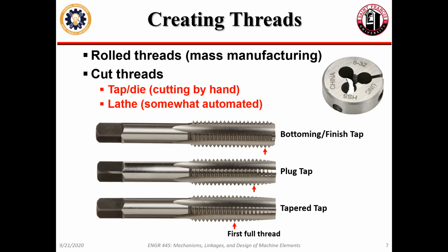The more threads you're trying to cut, the greater force there'll be on the tap itself because of how they're made. So most of the taps you'll see around here are tapered. So start from not really anything. This is like the minor diameter of the screw. It gets steadily larger and larger, which helps you to align your tap so it's parallel to the hole. There's more tap in the hole before it starts cutting. And then eventually you have a thread that's like way up here.